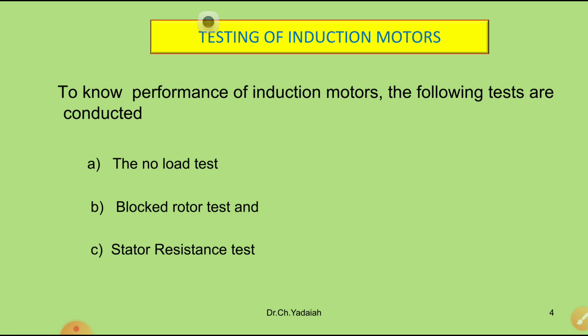To conduct the no load test of an induction motor, what are the requirements and what is our aim in finding the values? The requirements are a three-phase induction motor, an auto transformer to control the rated voltage, and one voltmeter, an ammeter and W1 and W2 wattmeters to find the power consumed by the three-phase induction motor. After conducting this test, what are the values we are going to find?